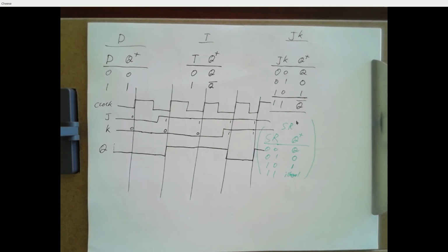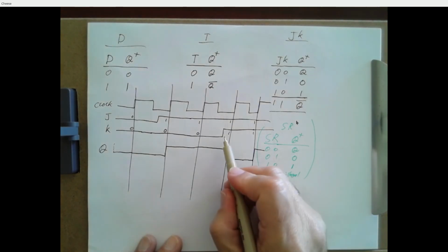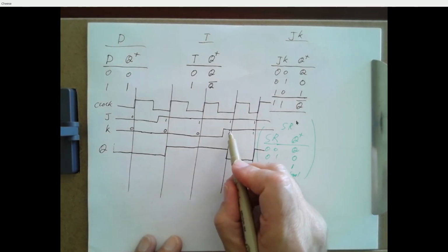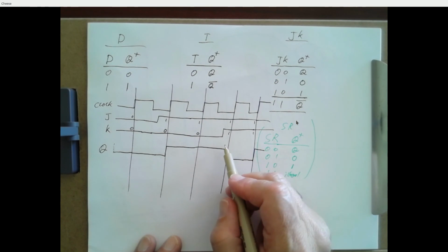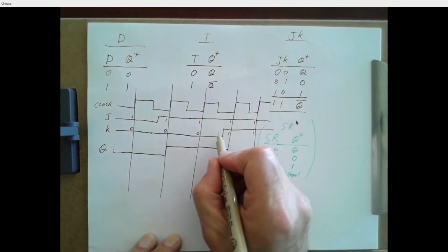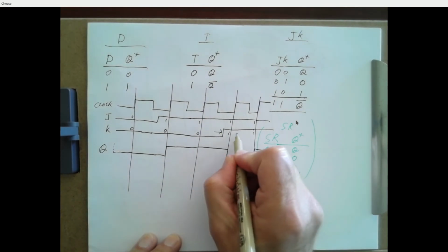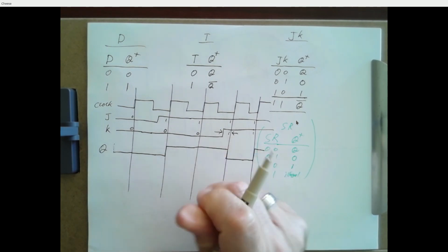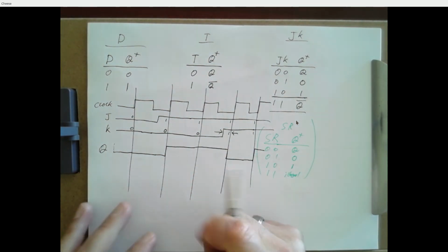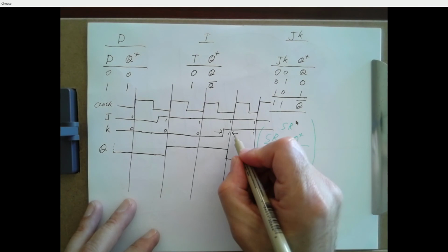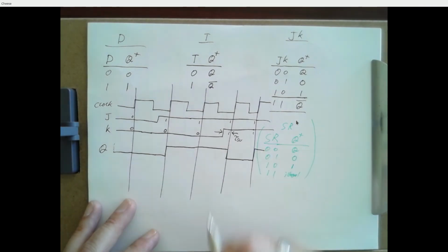But in practice, if I had raised this edge right before the clock tick, the system might misbehave. So we need to know that this input is stable for a certain amount of time before the clock tick. Do you remember what that time is called? That's the setup time, so tau SU.